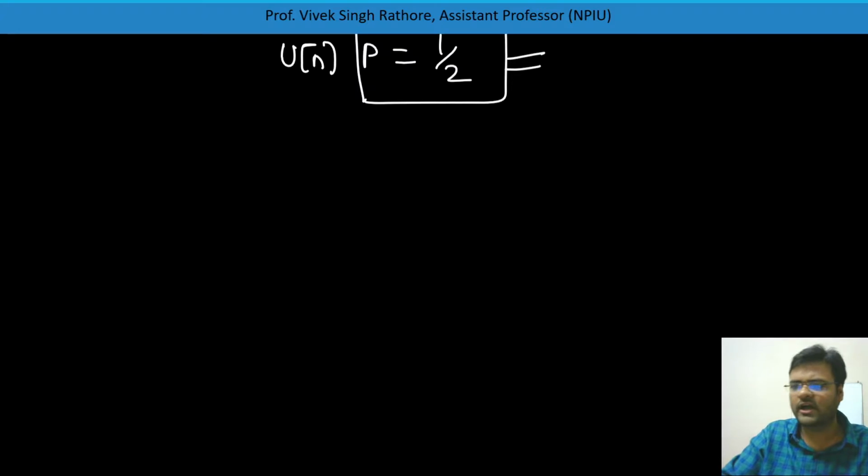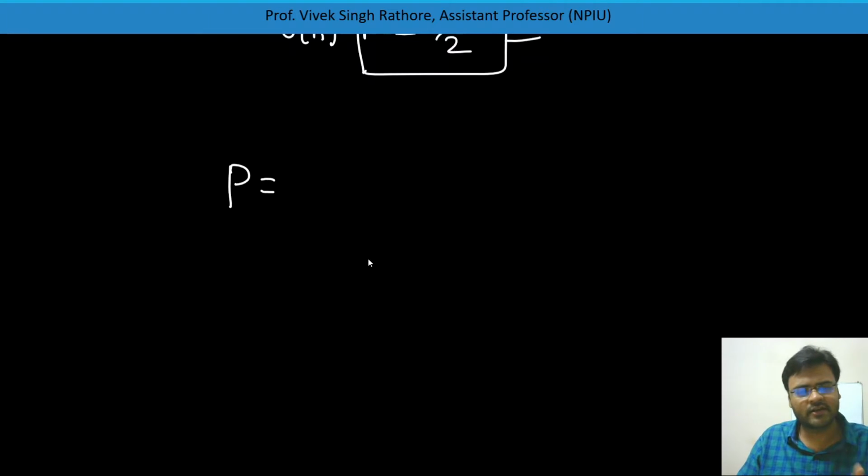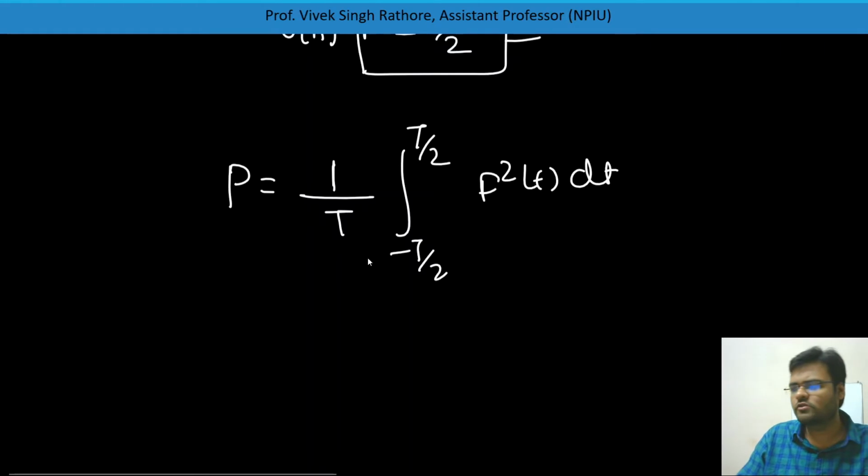One more thing I need to tell you: whenever your signal f(t) is periodic, then you can definitely calculate your power. Because if the signal is periodic, that means it is not an energy signal. So if it is periodic, you need to calculate power. For a periodic signal, we should not take the limit t tending to infinity, because if you calculate for one period, it is the same for other periods also. So what we can do is 1 by T, and minus T by 2 to T by 2, f squared of t dt. You can write it like this.